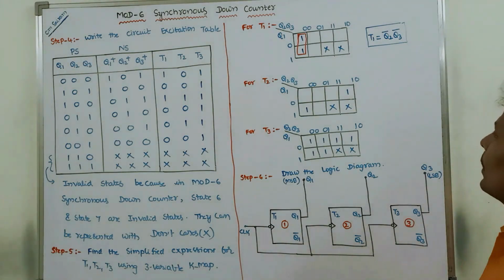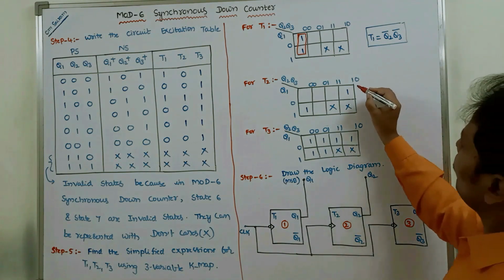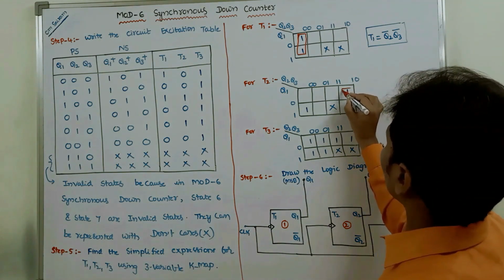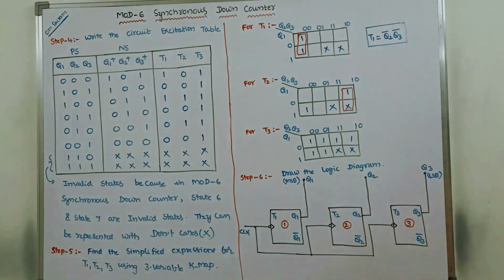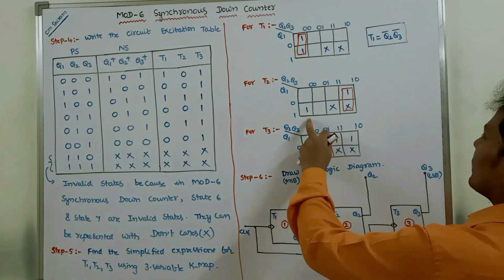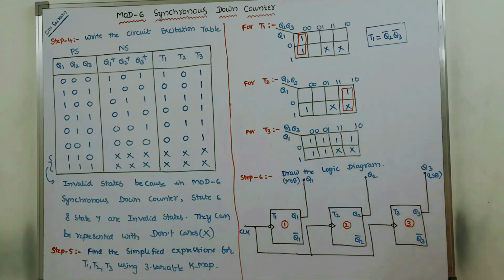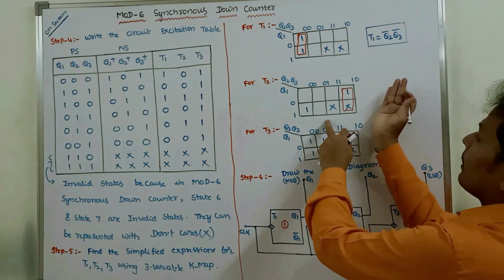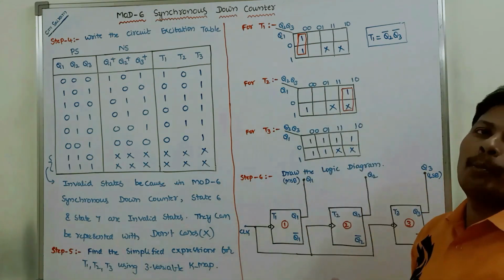Okay. So here, by observing this one and this don't care can be formed as one pair. Next one, in the corners are there, this one and this don't care also can be formed as a pair when we are folding the Karnaugh map from right to left in the middle.